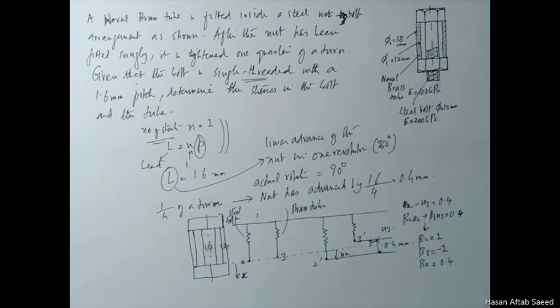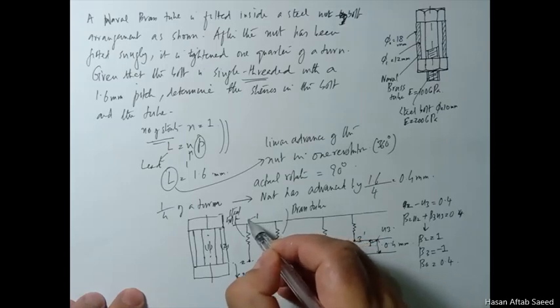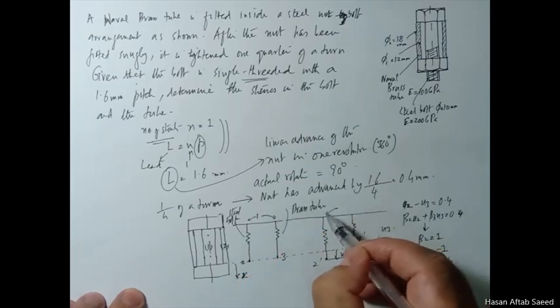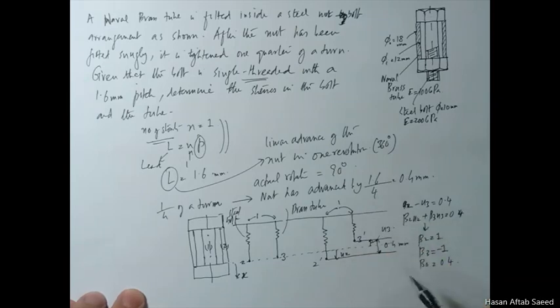Now this is one of the multi-point constraint problems. This you cannot do with simple application of specified boundary condition. There is no specified boundary condition. Yes, there is u1. This node 1 is common to both. This is 0. So in the interest of accuracy, you should also write that u1 is equal to 0. This is specified, yes.